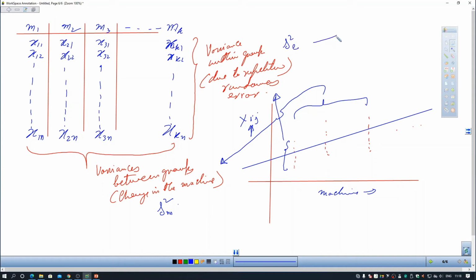That is only possible to see by taking the help of F distribution. F distribution is nothing but based on the random variable F, which will be the ratio of two variances which we want to compare, and that variances are compared based on the respective degrees of freedom nu1 and nu2 in the same sequence. Here in our case this is S of machine square upon S of error square.